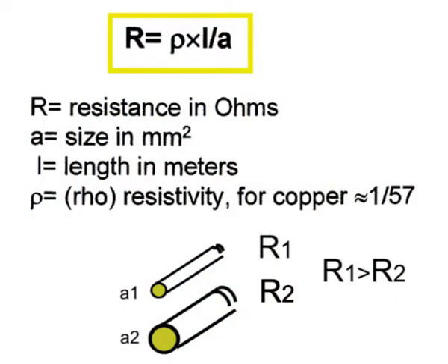There are several factors that will affect the maximum permitted current, such as room temperature, insulation material, and so on. Those calculations should only be made by certified engineers. For example, the formula shows that a thinner cable has higher resistance, and in contrast, the thicker cable has a lower resistance.